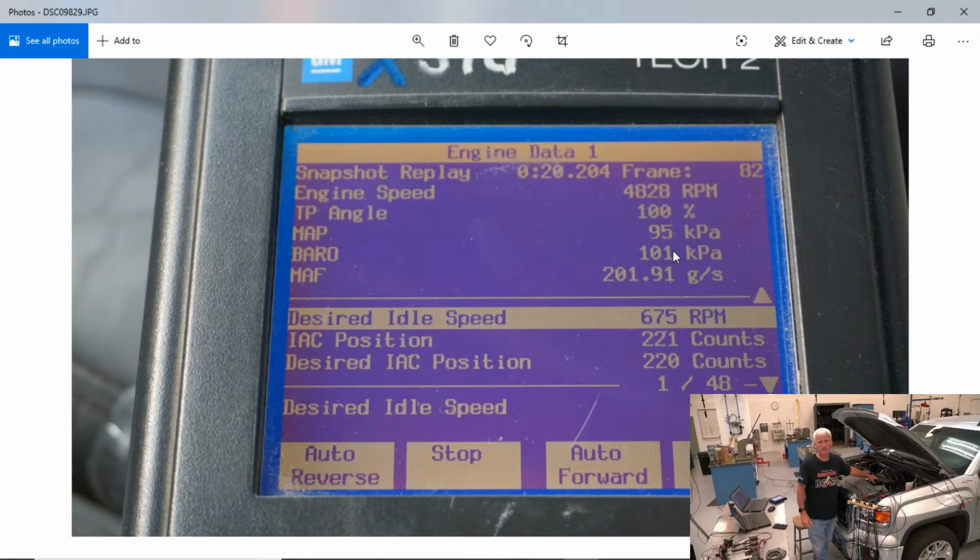Now let's say I got a restricted exhaust. If I got a restricted exhaust, how much air is getting into the engine now? If I can't get it out, I can't get it in, right? The restricted exhaust is going to prevent it from going out, so I got less air coming in because of the restriction in the exhaust. Well, guess what picked that up? I get less air coming in, so they mix less fuel with it. So you still have a stoichiometric mix, even though I've got less air coming in because of the restricted exhaust.